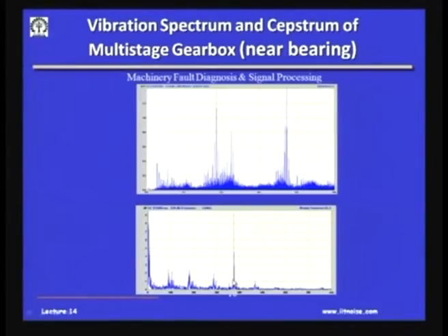If I come to the second plot here, they are all in time domain, and if you look here, the corresponding frequency will be shown, and you will know this corresponds to a particular rotational shaft of the gear, and then we will know its frequency content. From this frequency we will know this has a high amplitude, meaning this is the strongest sideband, and that is what Cepstrum helps us in.